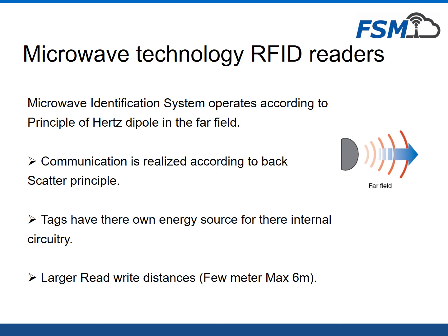And depending on the local regulation, how many milliwatts of microwave energy a reader can transmit, their ranges can be approximately 2 to 3 meters generally speaking, but extendable up to 6 meters, provided one doesn't breach the power safety requirements of the radiation.